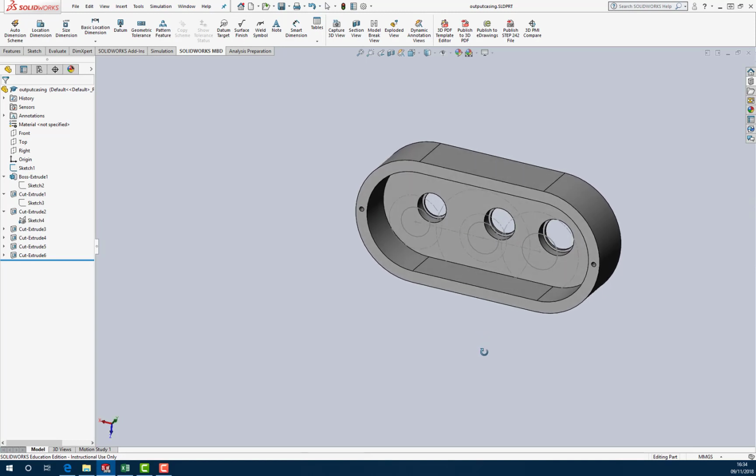Okay, so you should have looked already at, and we should already have worked out the tolerance values and the position tolerances and everything else for the bearings, and how to set up your datum system off the flat face and the two dowel holes to then be able to correctly position the bearings relative to the datum system.